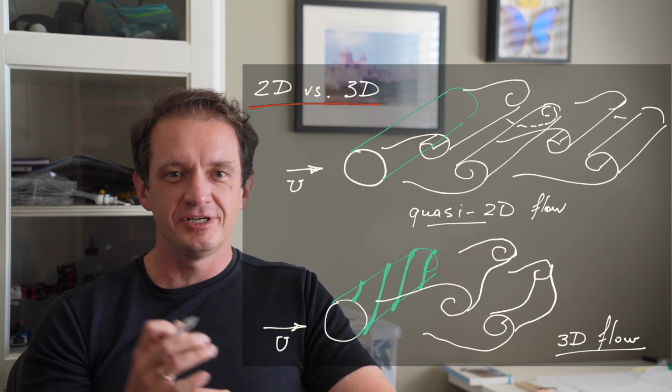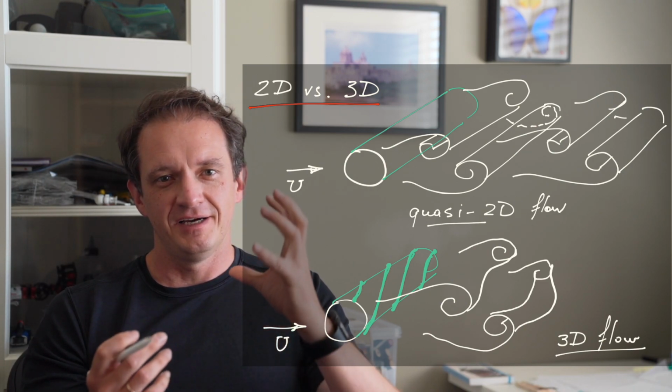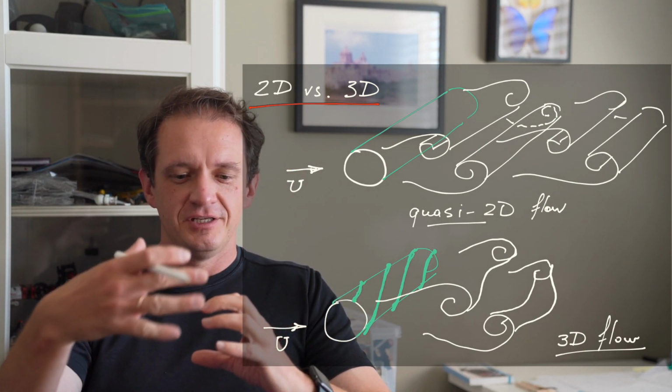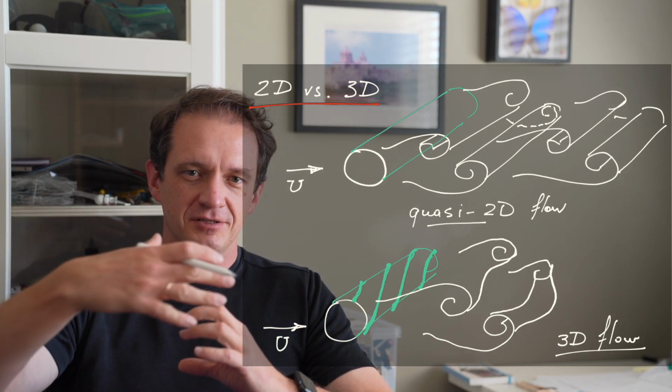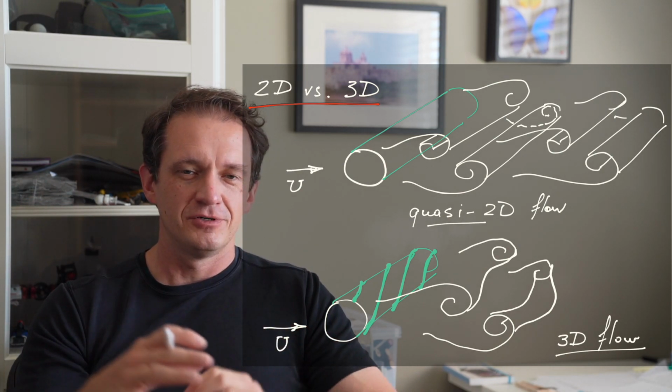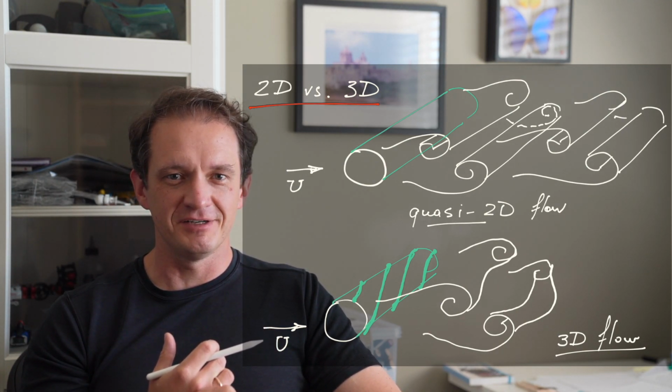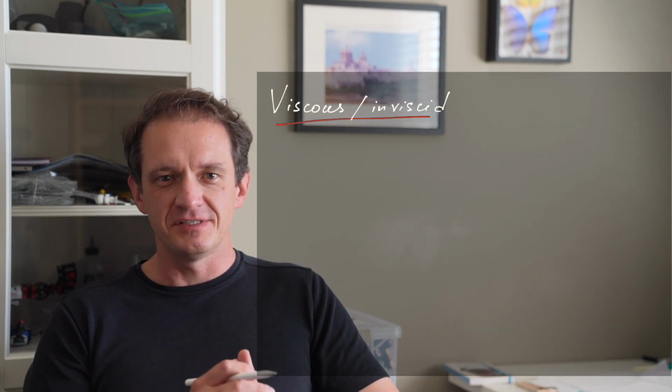Each vortex, as it's shed, results in a reacting force on the cylinder itself, and it vibrates. But if that shedding of vortices occurs at different phase along the span, then these instantaneous forces counteract each other. Well, there is an expense of an overall drag increase, but the vibrations are reduced. And you can see examples of these helical windings on car antennas or chimney stacks of power plants, things like that. So one of the main classifications that's the focus of this course is the viscous versus inviscid assumption.